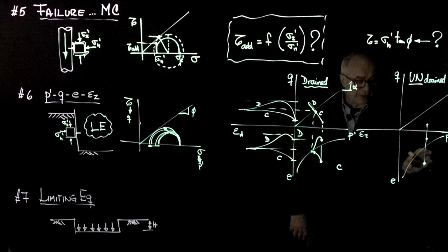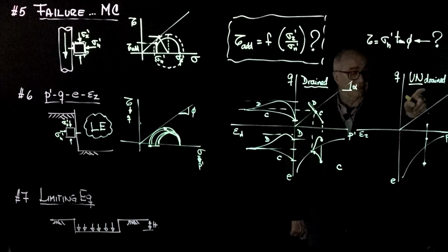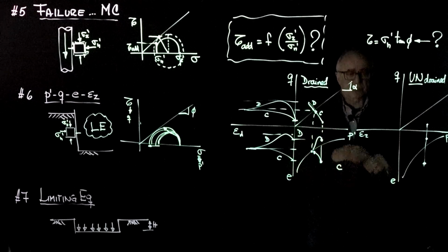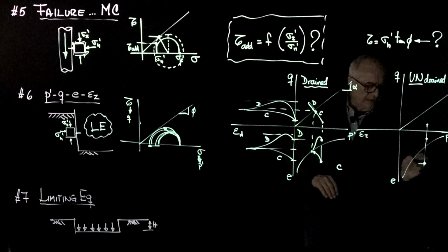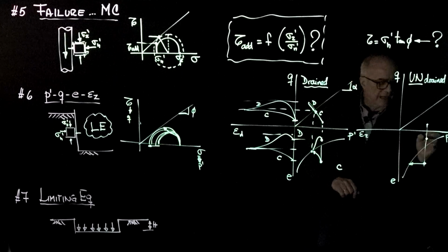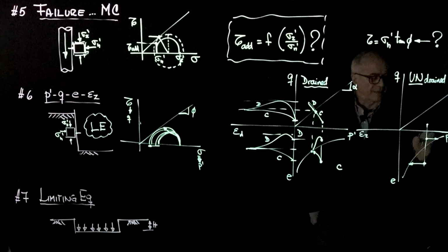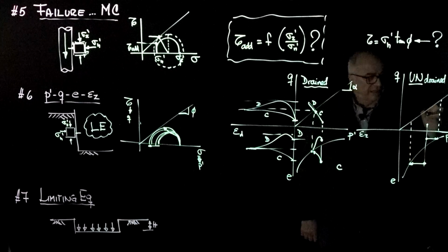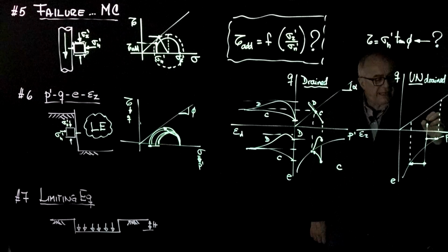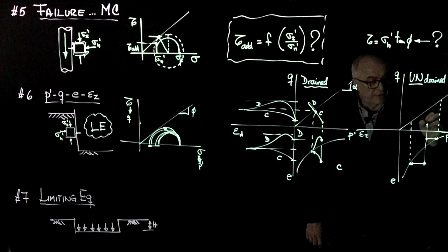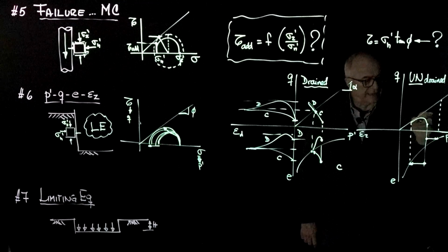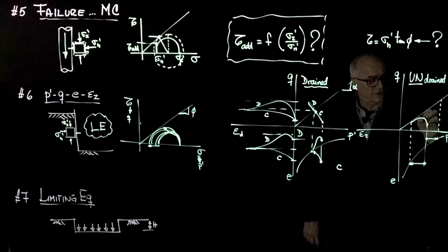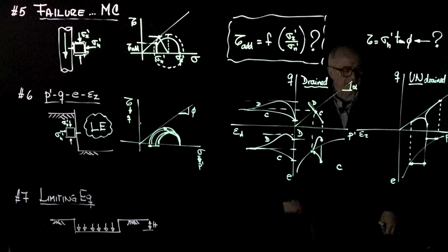But we do know what will happen in terms of void ratio, because if it is undrained and the system was initially saturated and there is no cavitation, this point has to find failure here, and the dilative one will find failure here. Therefore, we know where they will encounter failure, and now we go from the bottom up. This one will go like that, and this one tends to follow that, but eventually it goes in this direction. It tends to contract a little bit at the beginning.